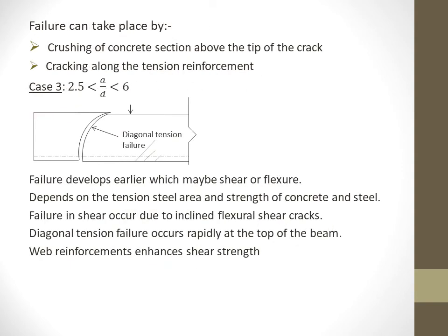However, when the loads and reactions applied on the top and bottom surface of the beam are so located as to induce a vertical compressive stress in concrete between the load and the reaction, the shear strength may be increased.